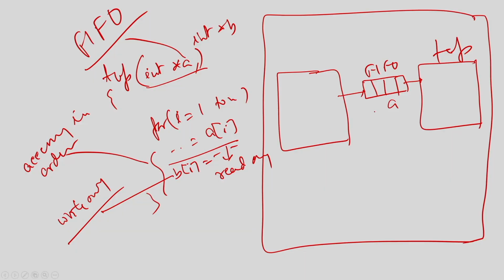These two modules, in the earlier diagram that I have drawn, are basically synchronous: whenever the data valid signal comes, it has to consume that data. But here this particular module can generate data into this FIFO in any different clock, and this one can read it at its own pace. So it may produce in every cycle and read it in every 2 cycles. This is possible because you do not have to make an explicit handshake between these accesses.